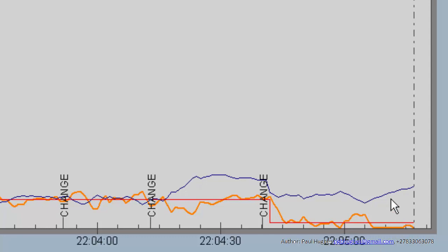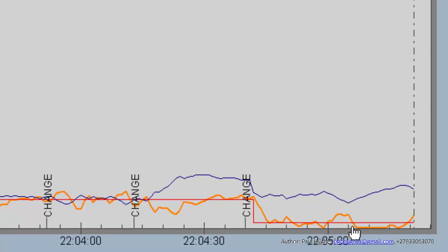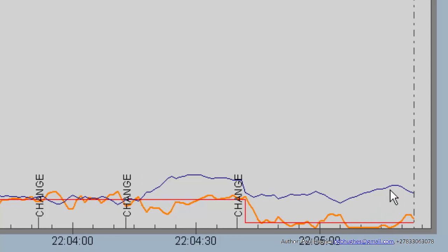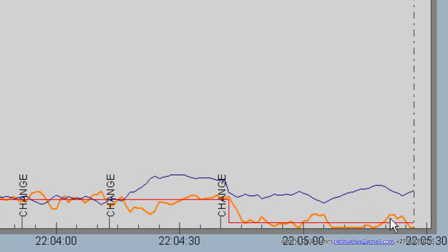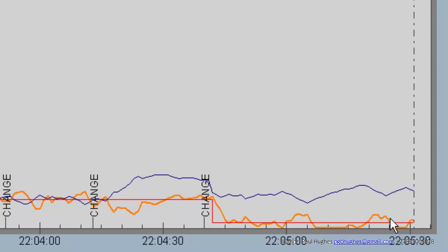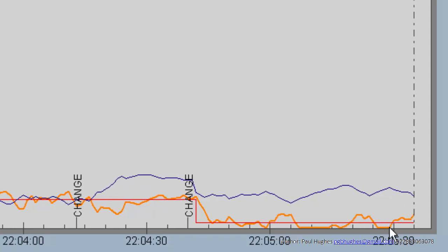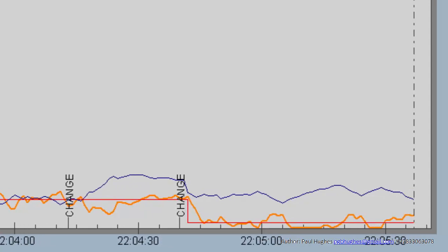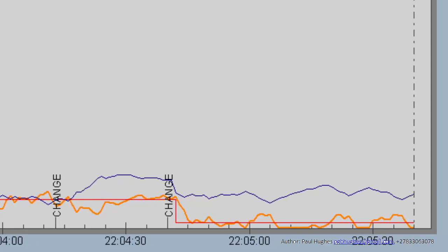So what happens now is the controller starts going through an oscillation at 0. It starts opening the valve until there's a flow measurement, and the flow measurement becomes valid. And you start getting a seesaw effect on the output of the controller. So I'll run it for a short while and I can demonstrate it again a little bit better.